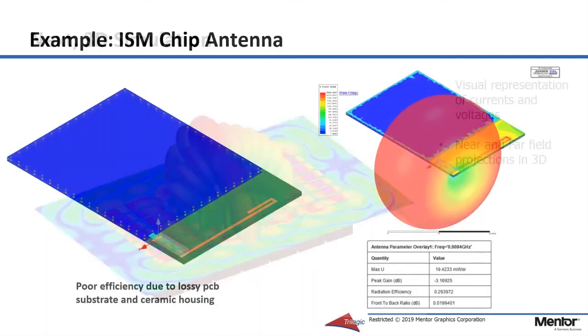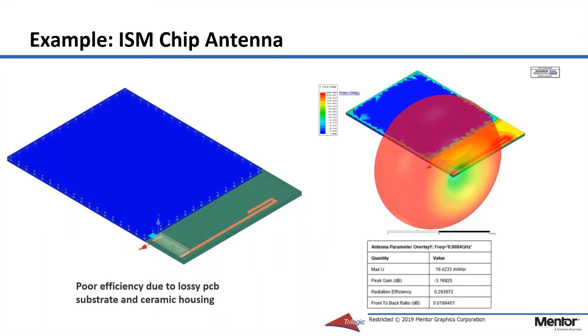So here is an IoT chip antenna and associated PCB laid out in PADS. The frequency is close to 900 megahertz. This happens to be a LoRa and Z-Wave range of frequencies. So it's simulated in HFSS after being exported by PADS. Here we realize some of the limitations of very small apertures. And you might say, well, why do you say that?